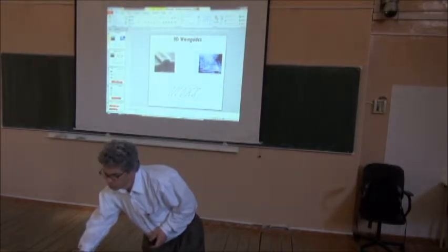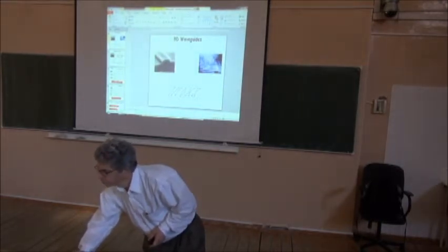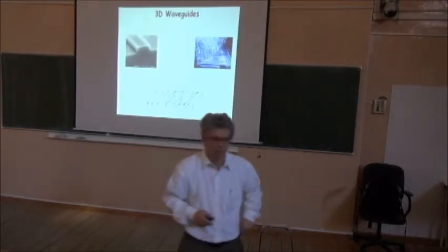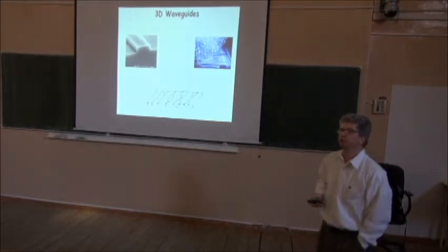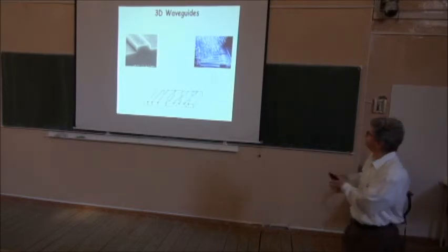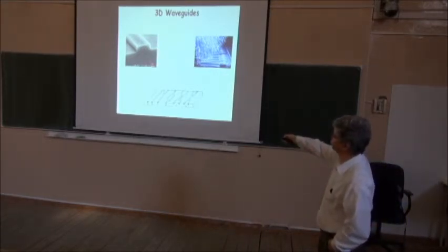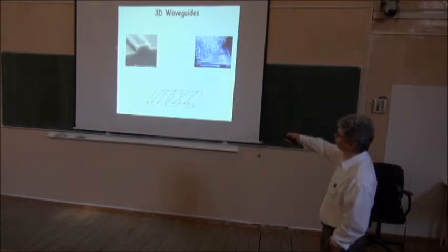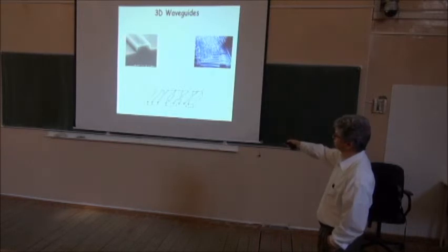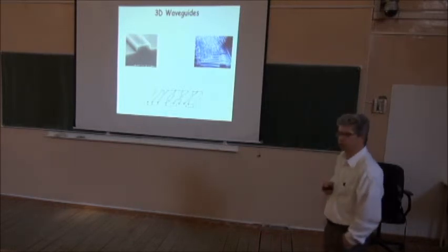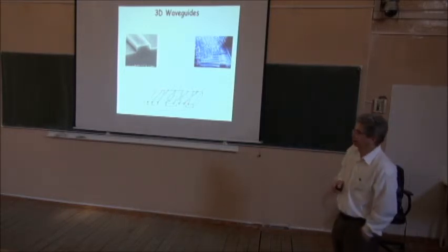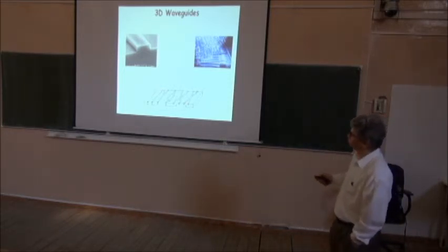So, changing topics now, we're going to start three-dimensional confinement. Up to now, we've been studying slab waveguides where we just have confinement along the transverse direction. Now we're going to make structures that also have lateral confinement. This is one particular configuration, and there are many, many devices that explore and need those configurations.